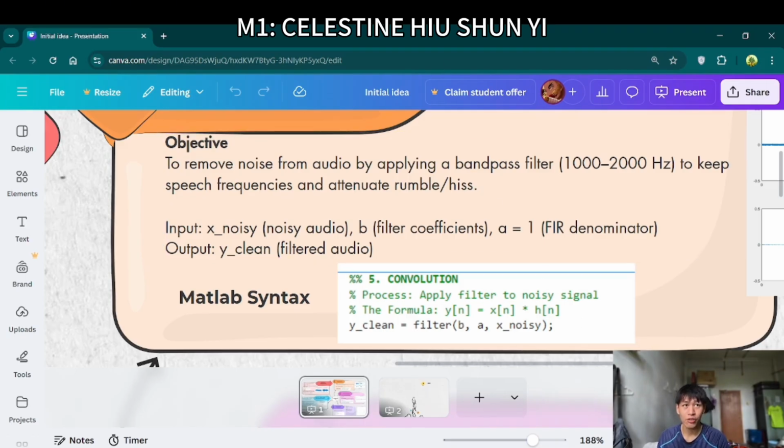The operation slides the filter across every sample of the input. Our input x[n] has 17,509 samples, and the filter impulse response that we use has 51 coefficients. After sliding, it will multiply and sum to produce each output sample.